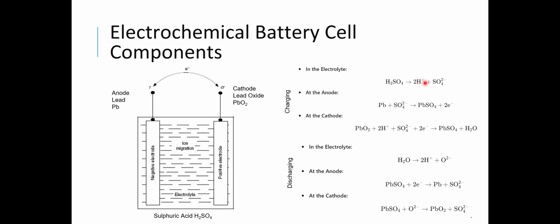And that's why we say lead acid batteries are abuse tolerant. Importantly, when I then discharge the battery, that hydrogen that was produced will combine with this oxygen. And when I have hydrogen and oxygen, I make water. So as long as this hydrogen that was produced when I'm overcharging the battery gets contained within the battery, and I can do that by sealing the battery. That's why often we talk about sealed lead acid batteries.